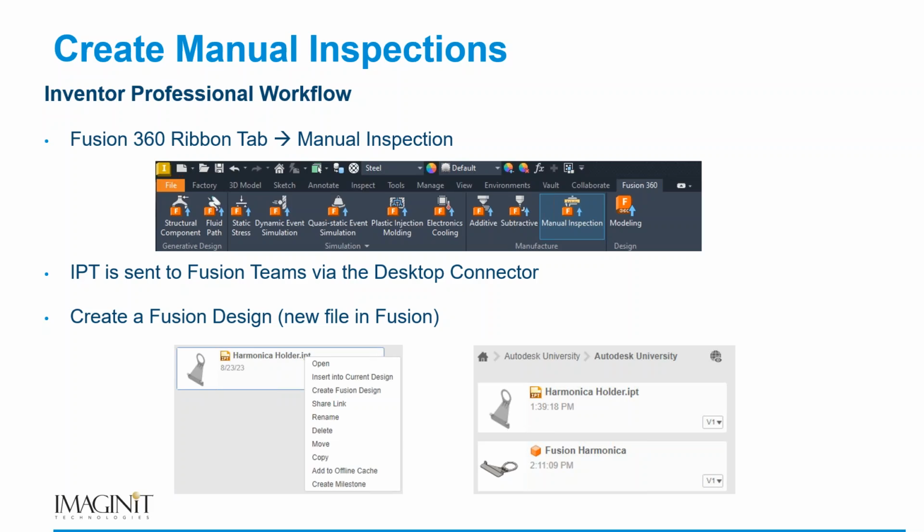And there's two ways to do this. Either you want to create a stitch in time separate file, okay, that's when you say Create Fusion Design, or if you just want to utilize that design so that when an Inventor model changes, the Fusion model also updates using any CAD, then you can carry forward the changes. You would simply say open and start working on that. It does convert it, but it keeps that link between the files.